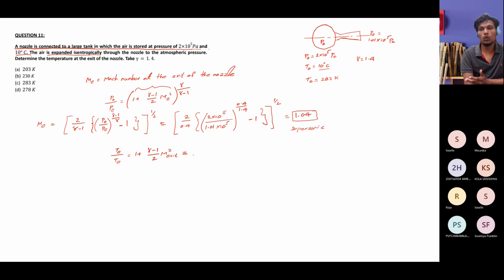In the last problem also we've seen that a shock wave creates a subsonic flow if the flow goes from supersonic to subsonic. So while you're calculating, if you get some kind of supersonic value behind the normal shock wave, you can verify that instead of directly putting in the value we get, by understanding the physics of it. Okay, so in that way, we see that the flow at the exit of the nozzle is a supersonic flow. That means definitely there should not be any kind of shock present inside the flow.